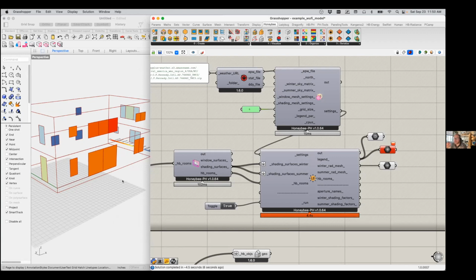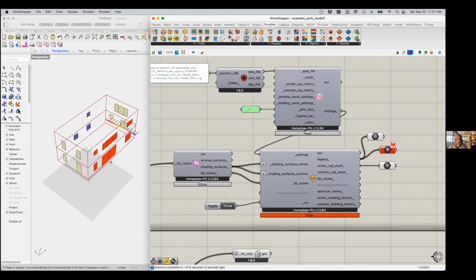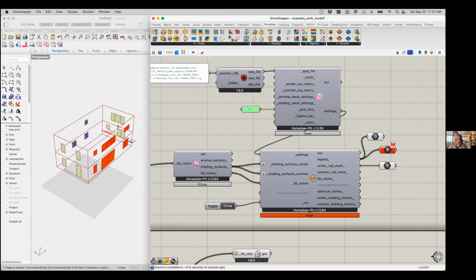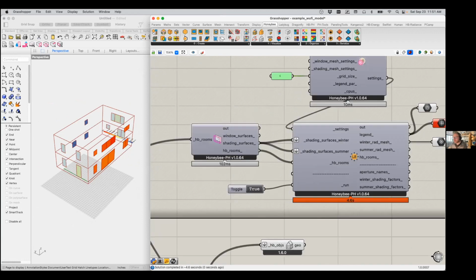What this will allow us to do, though, is to really more clearly visualize exactly how and where the solar irradiation is affecting our building, right? So we can immediately see that those south-facing windows are seeing much more solar irradiation than the east-west or north-facing windows there. And we can also do things like this. Currently it's only taking into account the self-shading from the windows.